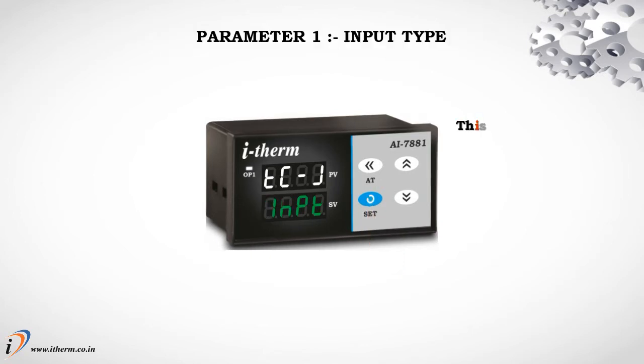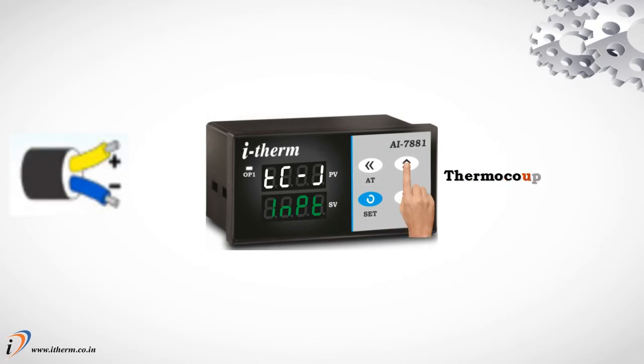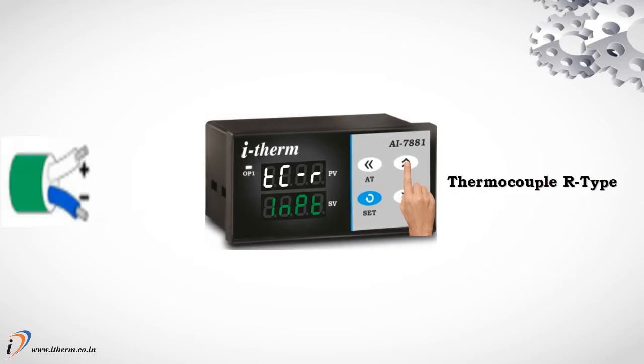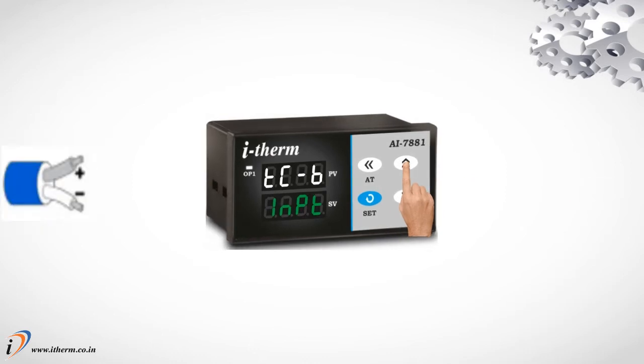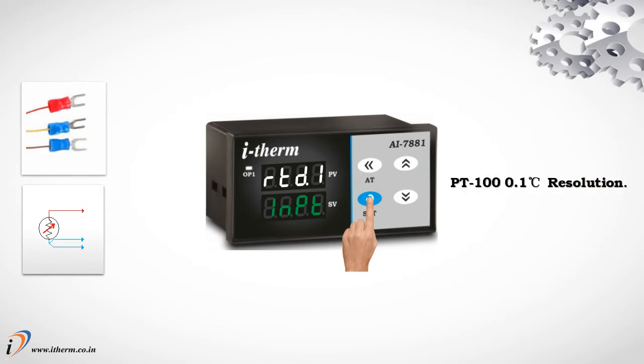Parameter 1, Input type. This parameter value is set according to the connected sensor type. Thermocouple J type. Thermocouple K type. Thermocouple R type. Thermocouple S type. Thermocouple N type. Thermocouple T type. Thermocouple B type. PT100 with 1 degree centigrade resolution. PT100 with 0.1 degree centigrade resolution.